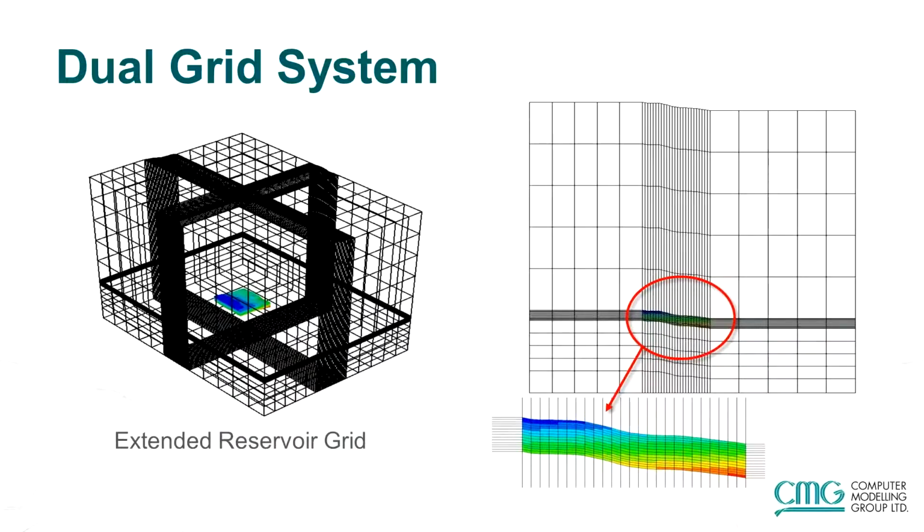It lets you add a geomechanics grid completely independent of your reservoir. So what happens is you have a reservoir grid which is just like you would do without geomechanics, and you create a second grid system which covers the length and breadth of the reservoir grid and goes beyond that. And it is extended all the way to the surface in this example shown by the black lines. And by doing that, you can represent the whole overburden, underburden, side burden, and a big area using very few grid blocks. And that's a very good approach, because sometimes we need to know what happens far away from the reservoir, and we don't want to solve millions and millions of grid blocks.